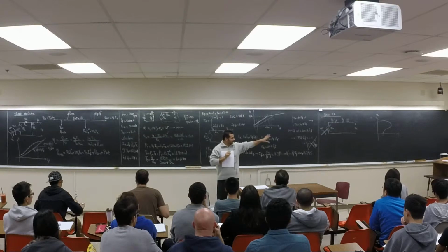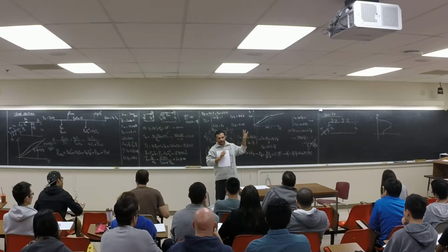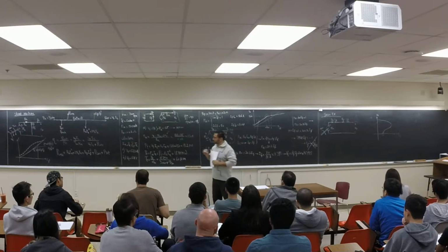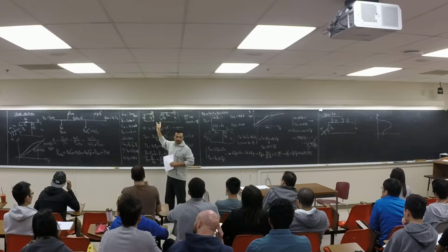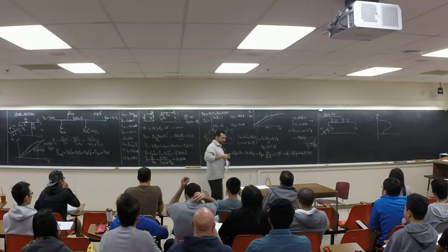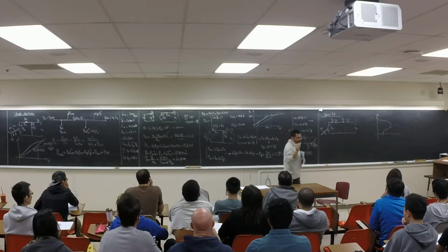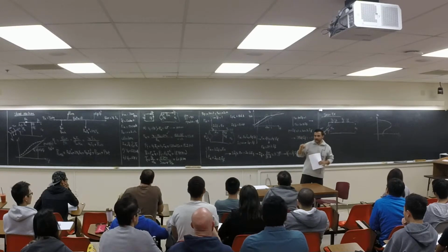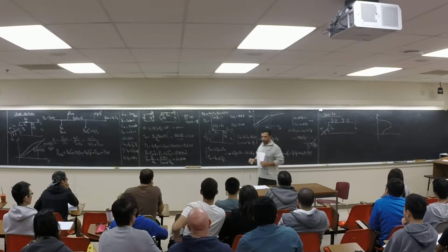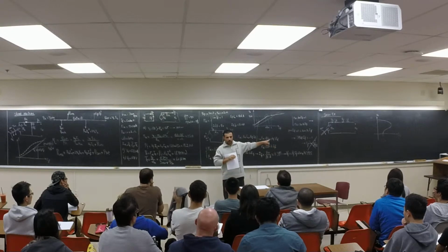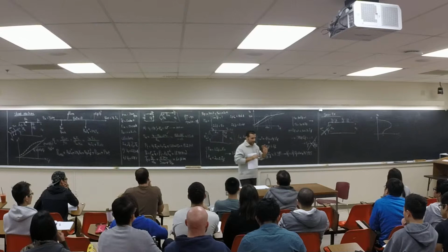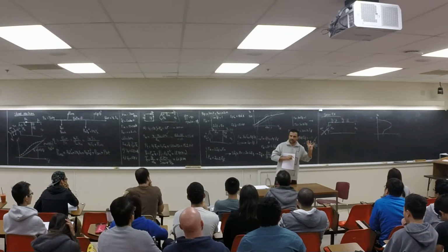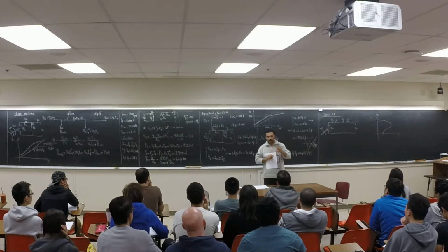So I'm saying series excitation, self-excitation, shunt excitation, they have different applications. The most common one is separate excitation. You can use it for motors, you can use it for generators, but it is for specific applications, for example, like welding, like drilling. For drilling, I'll show you why this series machine is very good for that. Based on a specific application, you can select different excitation.